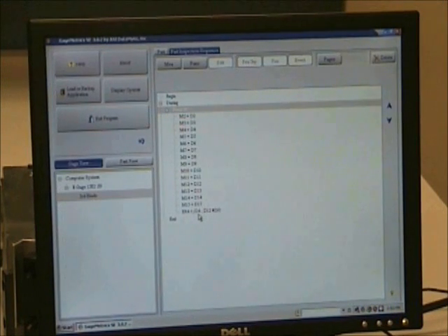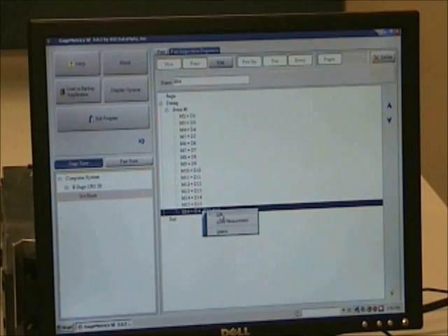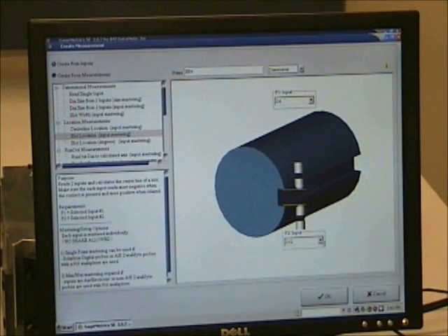The reason it's doing that is because we already used probe D4 once before and D12. And it's asking, are you sure you want to use those measurements again? Yes, I do. And so now I have created, if I go in and I edit this and I look, I can see that I have a new feature. However, I'm still using raw probe value. Sometimes you may not want to do that. You may want to use the M4 and the M12, which is the measurement from them, to create a feature. It depends upon your application.